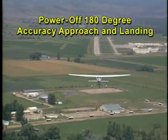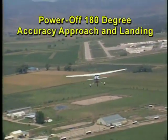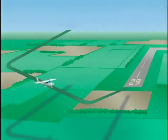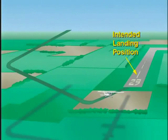Let's look at another maneuver, the power-off 180-degree accuracy approach and landing. It's an approach to land with the engine at idle that uses only the glide angle under prevailing wind conditions to fly a specific pattern and land on the runway at a predetermined point.